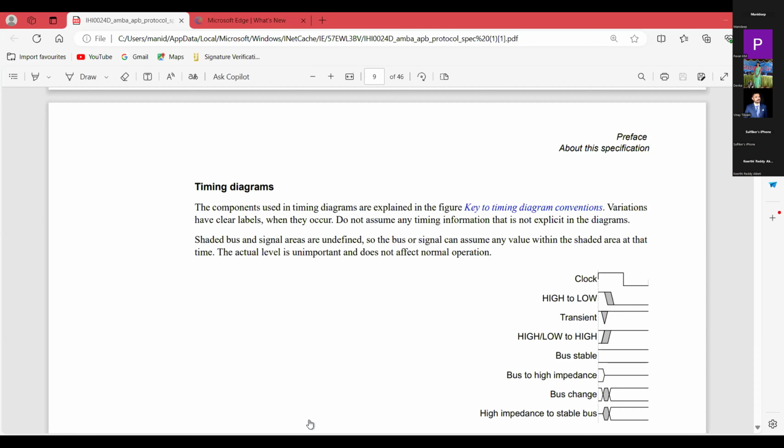That is the select signal, like PSELx if it is 1. What is P select, basically? It is a signal which we use in the APB protocol. It is generated by the requester and indicates whether a data transfer is required.